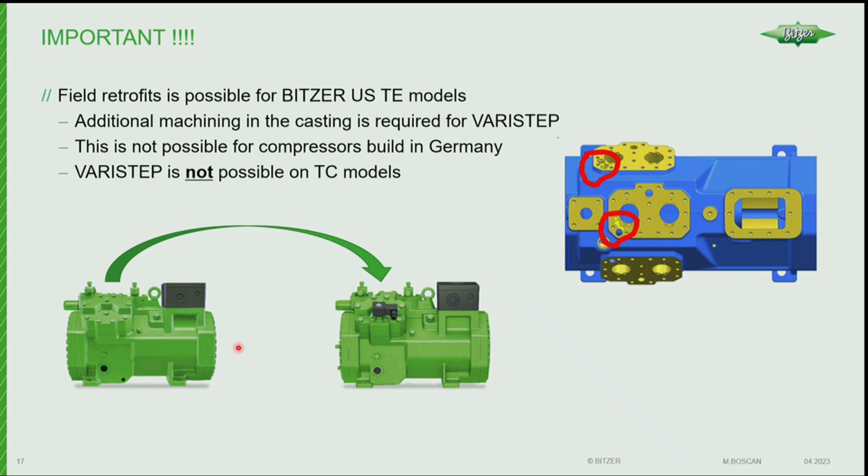And I'm not going to pretend that it's the greatest thing since sliced bread. VFDs are more efficient, though, because you're slowing down the motor. Here, you're basically cutting down the mass flow by just eliminating 2 cylinders. So the motor's still working and pushing up and down. You're just cutting down the mass flow. But there's some cost effectiveness, right? This is less expensive, especially for larger VFD motors. You get larger VFDs, and VFDs, in some cases, are more expensive than the compressor.